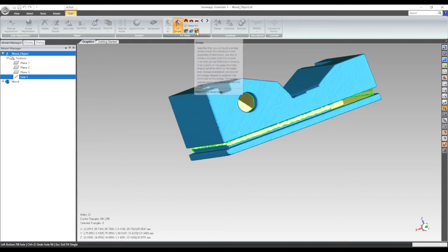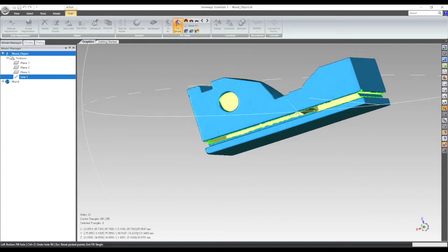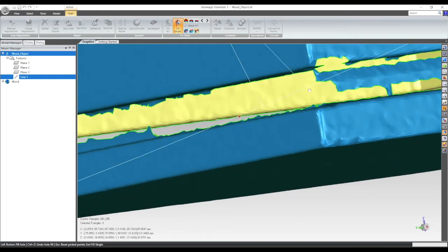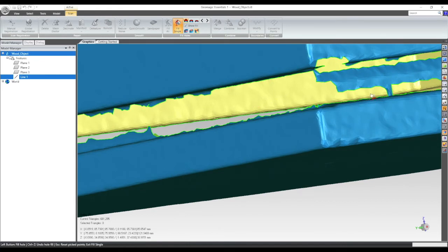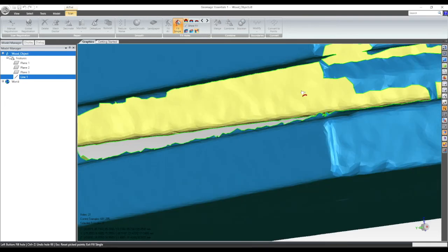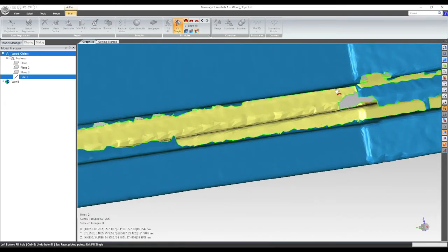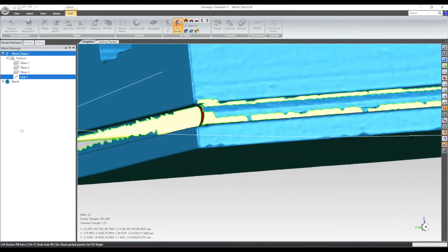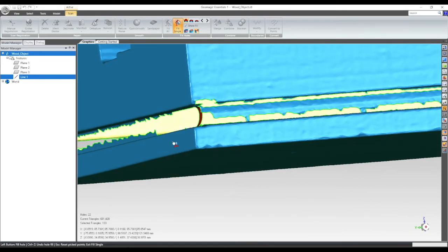Bridges are quite useful if it comes to regions, for example, like here, a region that goes around the corner. So on that side I want it to be flat, on that side I want it to be flat, but I need first a section of it. So I click on it, hold the mouse button, pull it a bit, let go of the mouse button, click it again, pull it, and here I have my bridge. So now I see, ooh, this is not what I really wanted. So I click Control and C, then it's back.